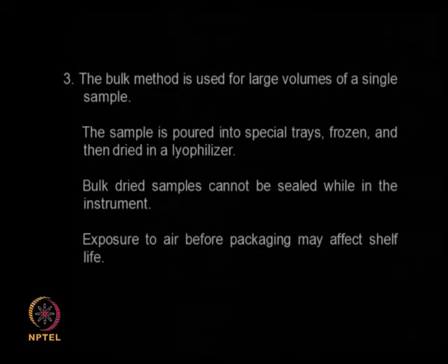If you have large volumes of a single sample, then what do you do? You can pour the material into special trays, freeze it, and then dry it in a lyophilizer. But one thing is, you cannot take these samples and again seal them separately, because if you do that, you are exposing them to air, and sometimes oxidation may affect the product quality or product stability.